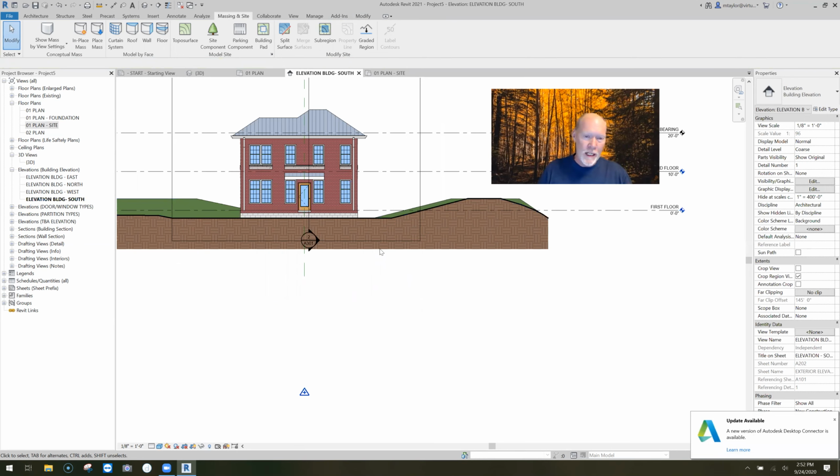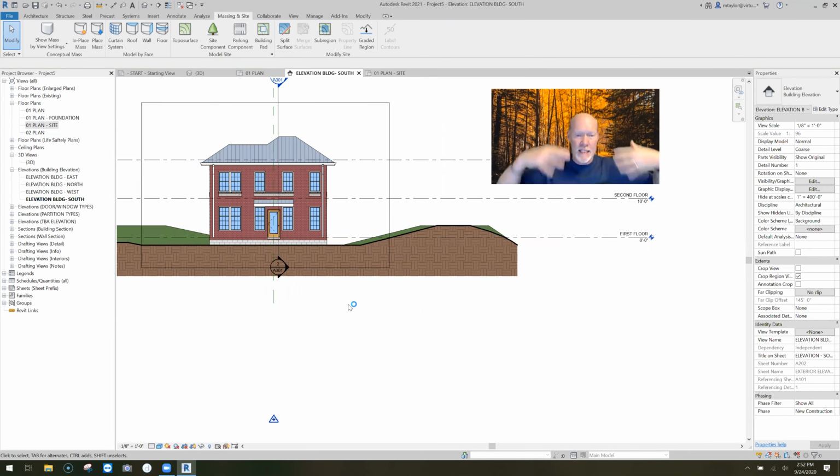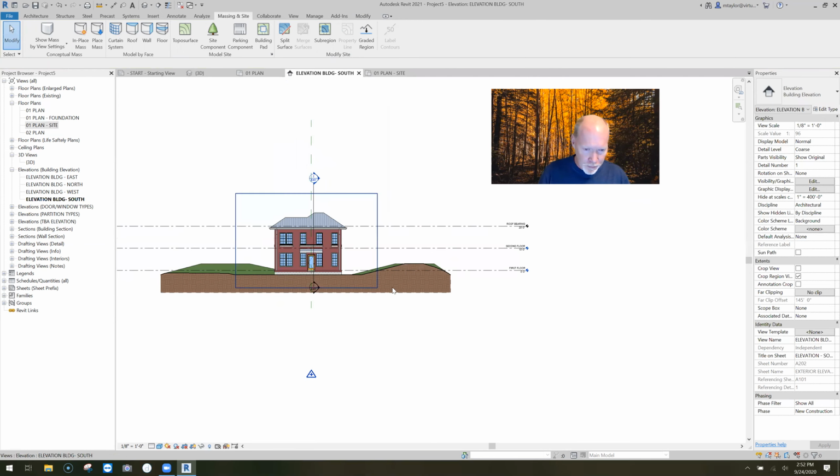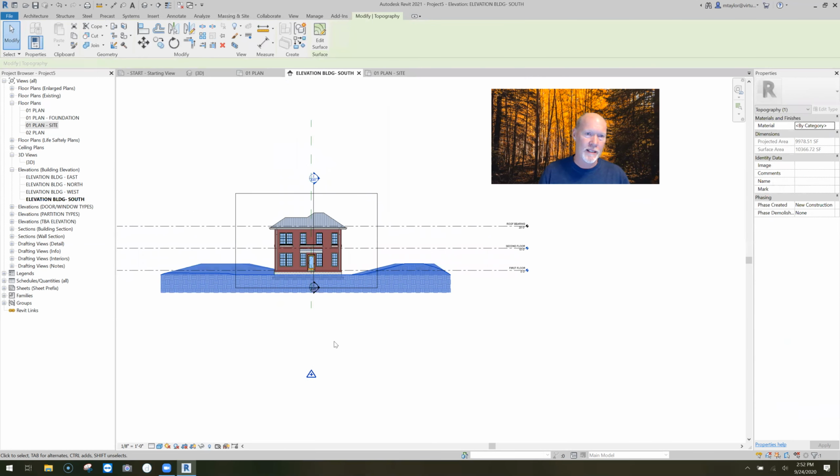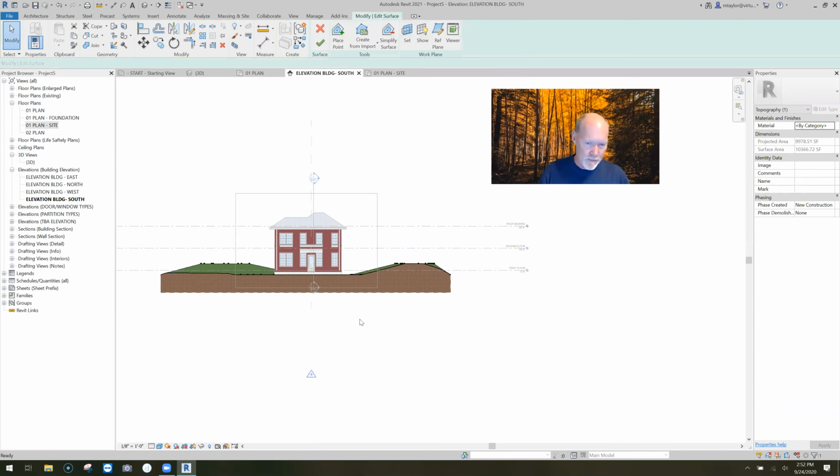So what I need to do is get this site back where it belongs and then move my building to it. So when you get yourself all in a pickle and you're all messed up and you're just moving things to make other things work, stop. Just stop what you're doing for a minute. And here's what we need, okay? What I'm going to do is pick the site. I'm going to say edit surface, okay?